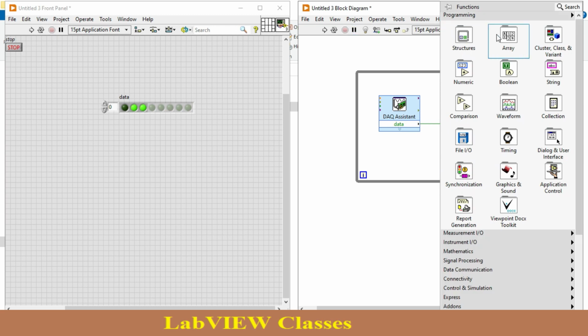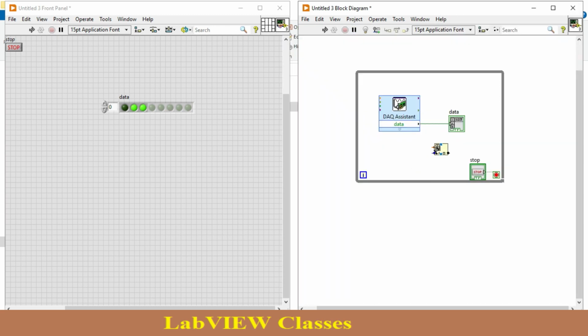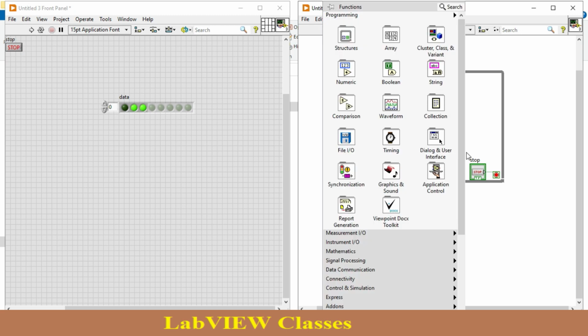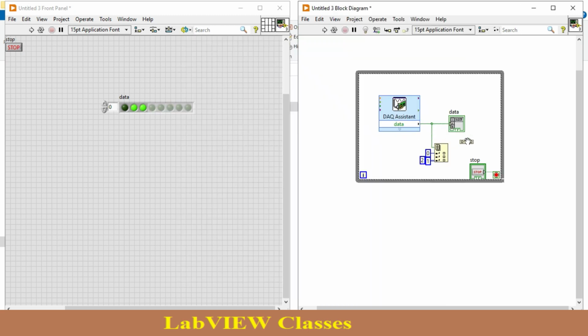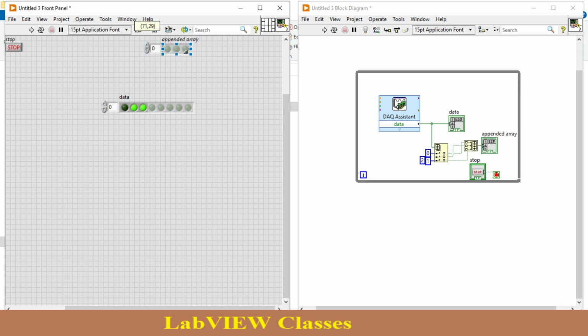It is based on my case. When I connect this, in this case I want 3 signals. Let's say create 0, 1 and 2. Over here I have 3 different values. Now it is up to you where you connect this one. According to this, it will generate values. I just use the build array function. I connect this one over here, this one over here, and it will generate an indicator that has only 3 values.